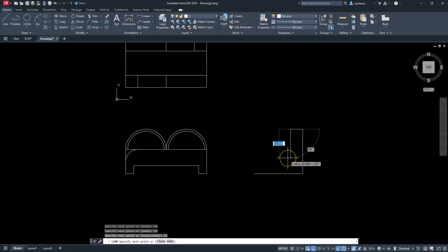So now this is where we have to do a little bit of math, and if you want to pull out your calculator, you can do that, or we can use the calculator inside of the AutoCAD command. So if there's a lot going on, or you just don't feel like doing math, aim in the downward direction, type in apostrophe CAL, hit enter, and in our case our numbers are going to be 55 minus 15, right? Hit enter, and it will do the math for us. You can see that that number is 40.